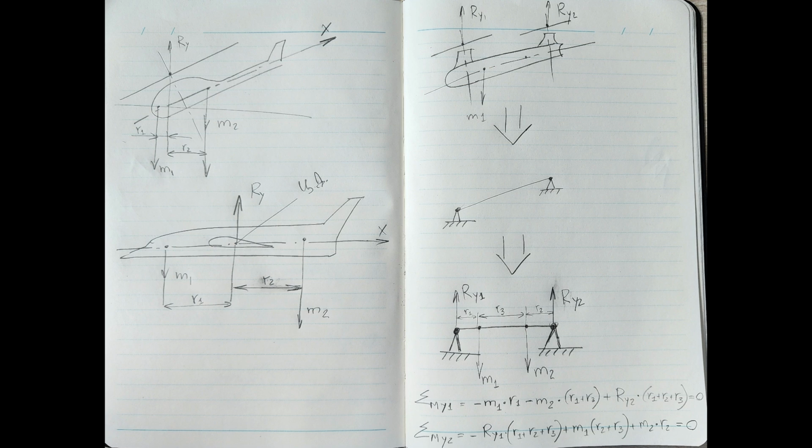With regard to hexacopters, octocopters, and other UAVs with even more rotors, the alignment calculation scheme, oddly enough, is even more simplified, because the more electric motors are installed on the so-called wheelbase, the more the calculation model begins to resemble a distributed load applied to a conditional circular frame connected to the center of the circle by pylon beams.